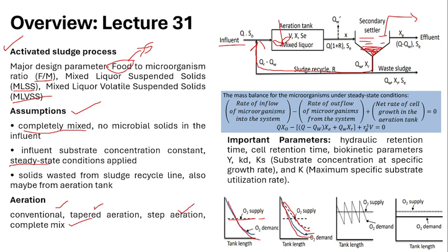And in the step aeration, we are just giving the O2 in a stepwise manner. We are going to open the O2 circulation for some time and stop it for some time. So on and off conditions are included in this step aeration. And now in the tank, the fourth one, we are going to purge the O2 entirely. Sufficient O2 is supplied and complete mixing of oxygen is going to happen. So these both are equal. This is completely met by the O2 supply.